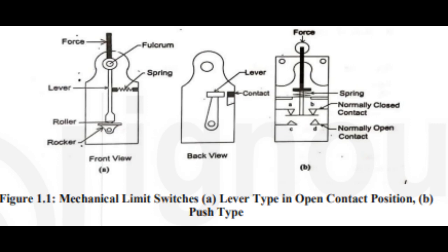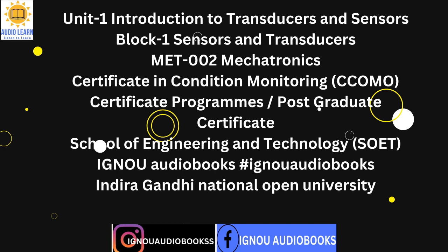1.4.2 Proximity limit switches. The term proximity switch, sometimes called proximity sensor, refers to a non-contact sensor that works on the principle of inducing changes in an electromagnetic field. The proximity switches most commonly used in the manufacturing environment are the inductive proximity switch and the capacitive proximity switch.